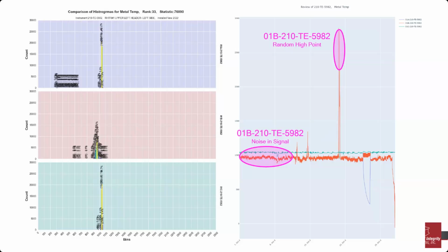So the total plant output is somewhere around 250 or so megawatts, which really helps us to manage the solar. We'll turn down these units daily during the peak solar output around 3 in the afternoon, instead of having to cycle them on and off. So that's been a big part of our flexibility initiatives.